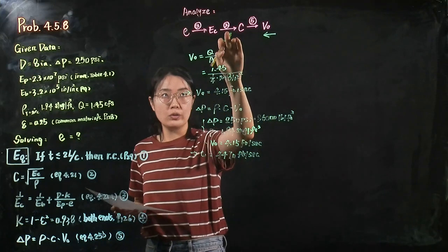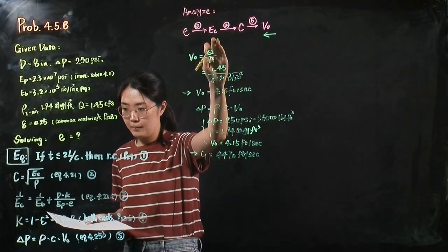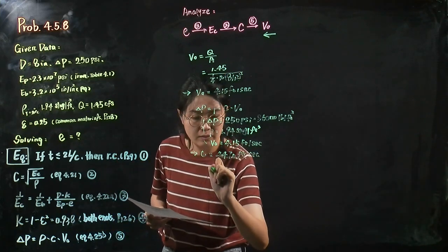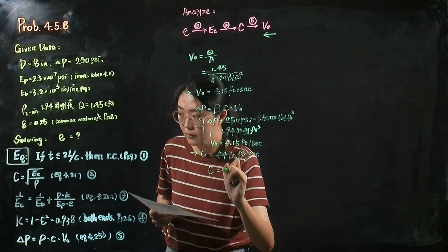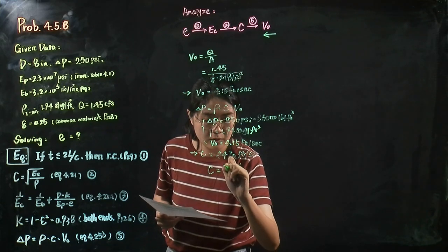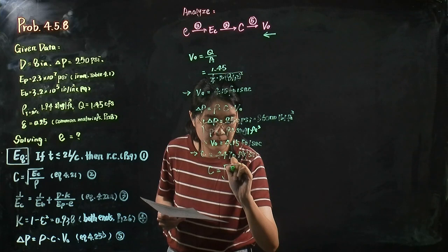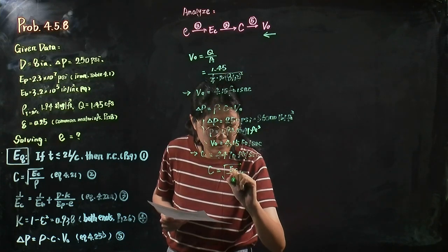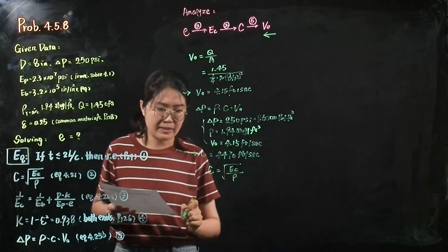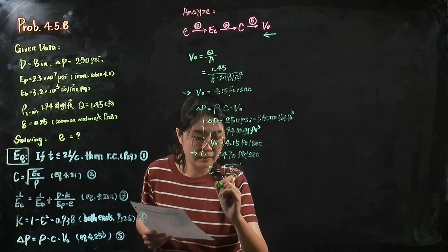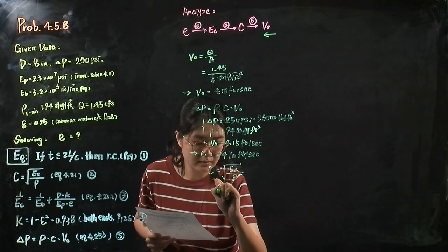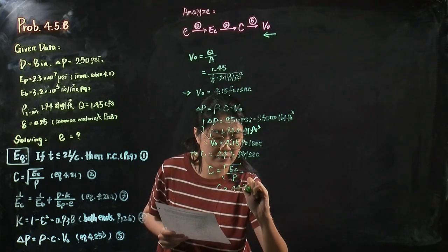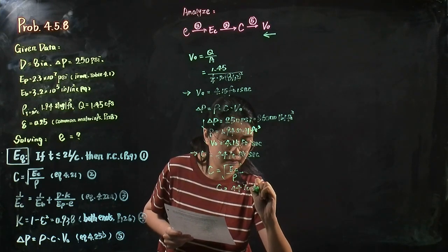Then based on equation 2, we can calculate the composite elasticity. The celerity equals the square root of the composite elasticity of the system over the water density. Because the celerity equals 4,470 feet per second.